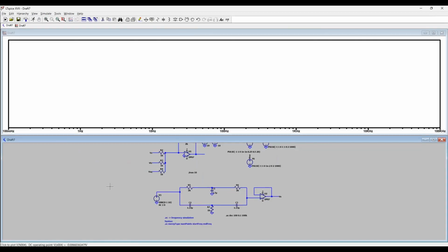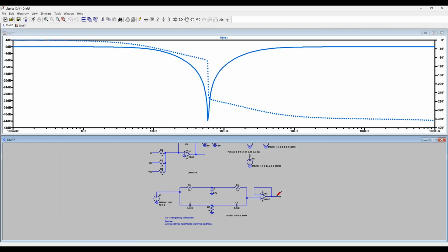we can see that if I click the output of VS, we can see that we have a characteristic notch filter where we're only filtering out a certain frequency. And we're based around 0 decibels, which makes sense because there's no gain involved. We'll get to that later. But if we take a look at our cursor and hover over the very tip of the circle, as we can see in the bottom left corner, our x-coordinate is at 59.5 hertz. So it's close enough to 60 hertz, indicating that our filter is working properly. And so this is the characteristic output of your notch filter.